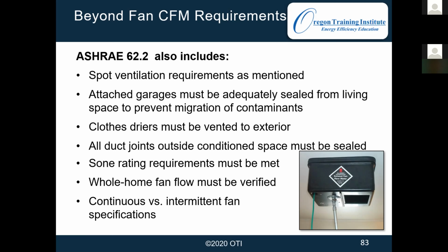For example, let's say ASHRAE, we run our formula and it says we need 40 CFM continuous. Well, if we have an 80 CFM fan and we run it half of every hour, or we run it 12 hours on, 12 hours off, that's going to be the equivalent of that 40 continuous, but on an intermittent schedule. And a lot of agencies are opting for this, I think, in hopes that it will help keep the fan from getting so dirty as easily when it's running 24/7.